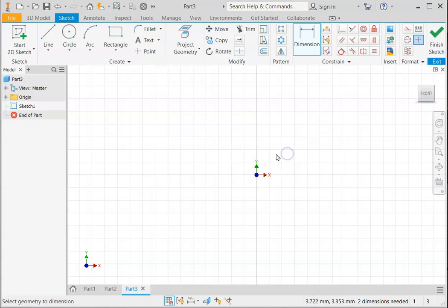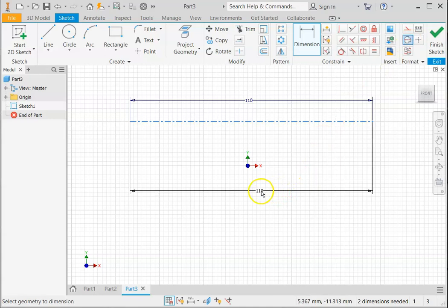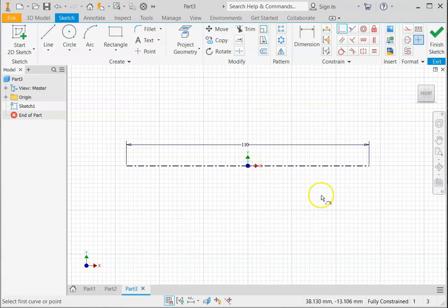This is going to be a center line. Select and change the line type. Move the center line's midpoint to the origin. Select coincident. Move your cursor until you see that little green mark. That's the midpoint. Select the origin. By 2 points coincides, it is exactly equal distance from both ends.